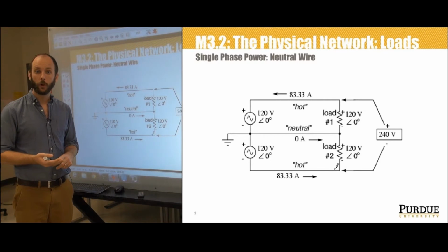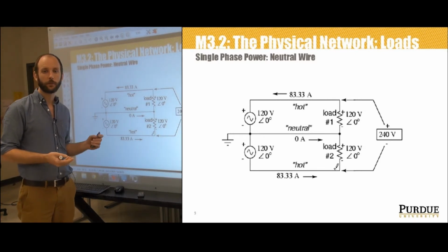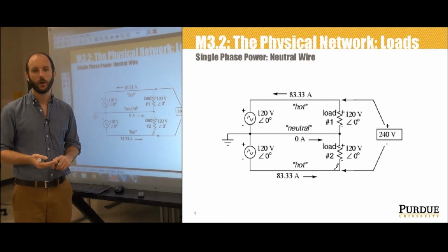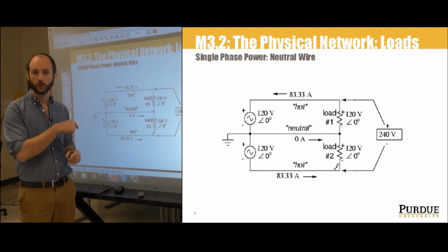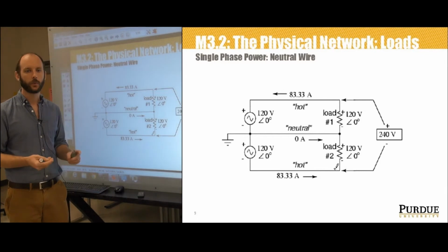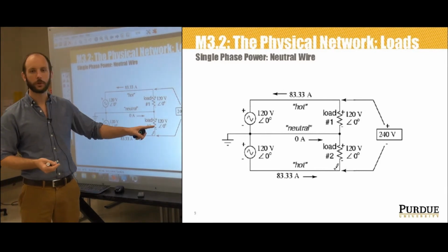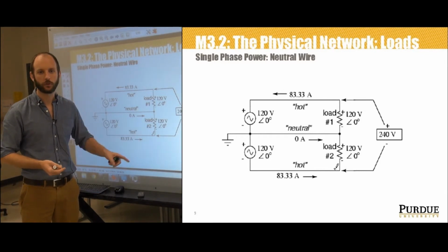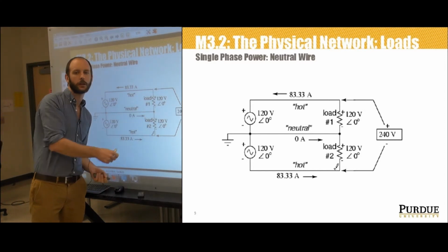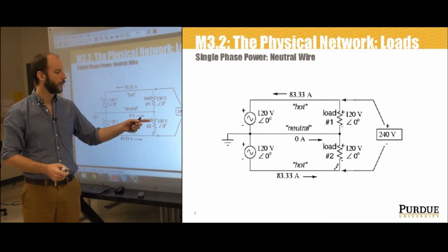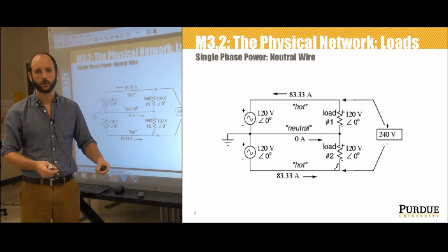You can use 3 smaller wires. It's more expensive than the 2-wire system we just showed, but it's still cheaper than the 2 wires needed in our original 120 volt design, and the risk of shock to a customer who would be located at one of the connections to the supply at an actual electrical device, where the customer is actually plugging his electrical device into the plug, is low because it's down to 120 volts.